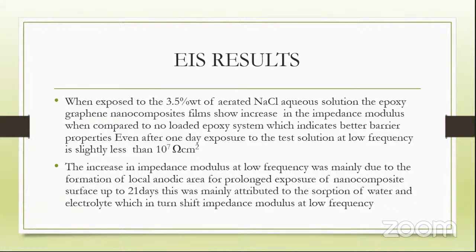And this increase in impedance modulus was mainly due to the formation of local anodic area for longer exposure of nanocomposites, say up to 21 days that I have tested, which was attributed to the absorption of water electrolyte, which in turn shifts the impedance modulus to lower frequency.